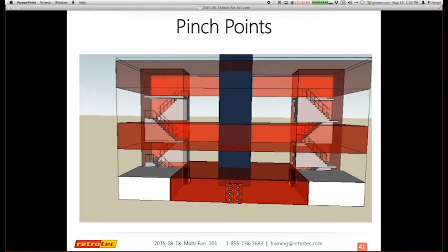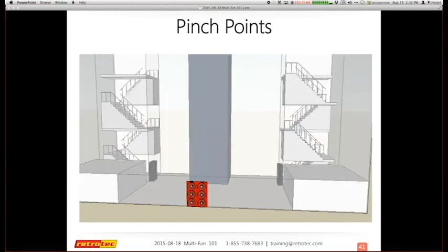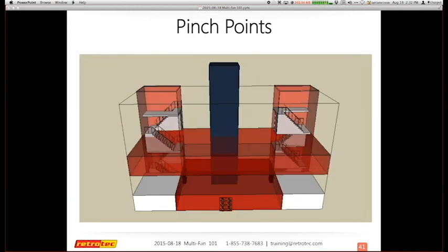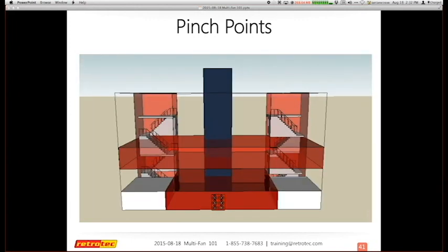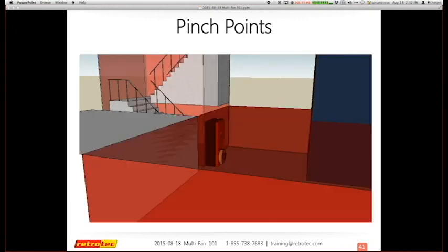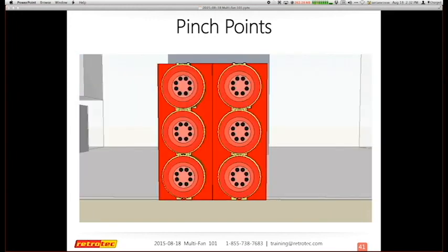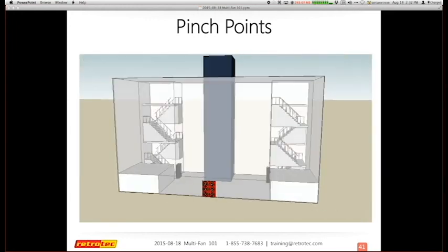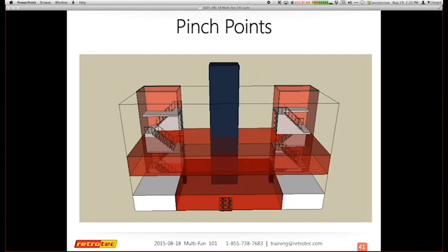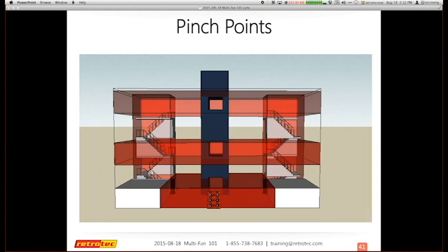I made this as a SketchUp model. We discussed this at our Seattle training. It's one of the things we talk about at other trainings. So one scenario here, which will repeat itself, is that I've got a bank of 6 fans. And the challenge is how do I get all of my pressures all the way up to the top floor? Because I'm going to use the stairwell as my ability to move the pressures throughout the structure. My ability to move the pressure throughout the stairwell is limited by the opening in the doorway on each side. So some other alternatives are to add a fan to what's called boost the pressure, which basically just means I'm going to try and help that door opening and add another fan in there to help move pressure throughout the structure. It doesn't read anything.